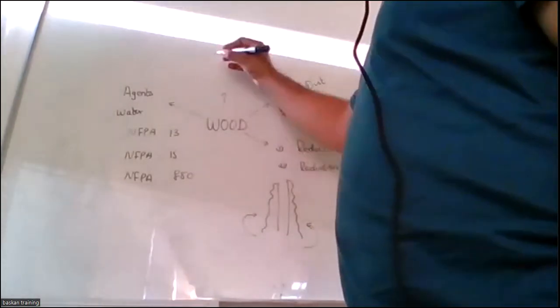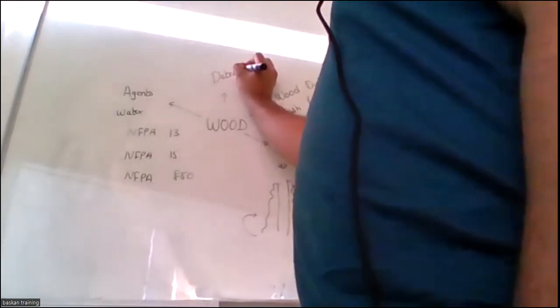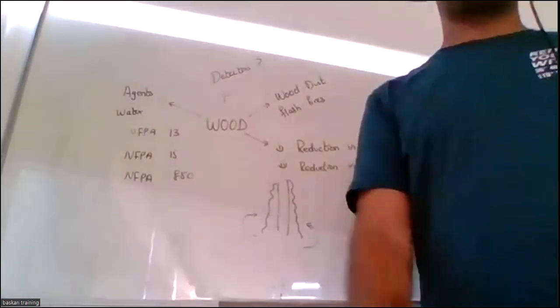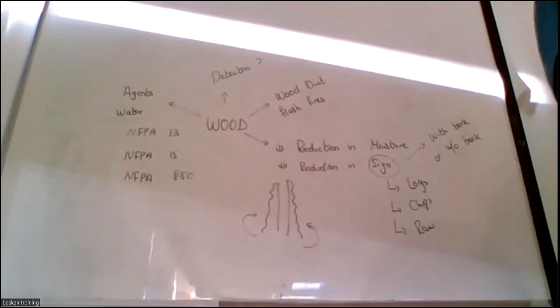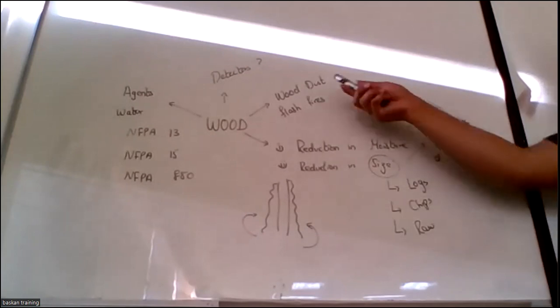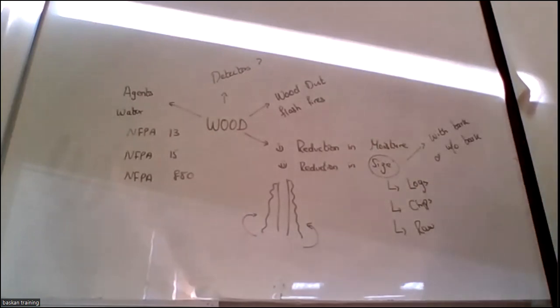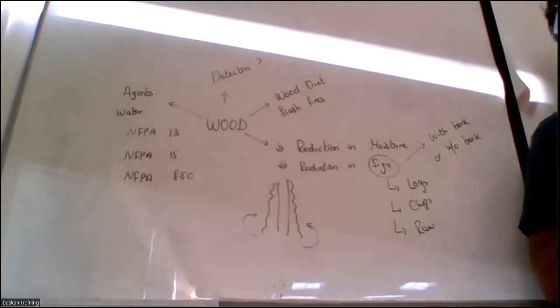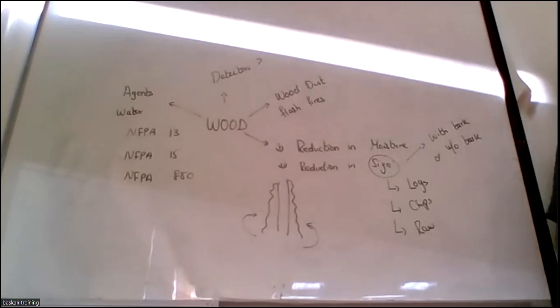What about detectors? In which storage area, what type of detectors can I use? Dust, smoke detectors, false alarm. Actually, we have seen a lot of installations. Personally, I have experienced one of the installations in one of our projects: wood cutting, furniture industry. They're cutting wood, they're making furniture. In that area, they installed smoke detectors, and every 2 or 3 minutes that detector was triggering.